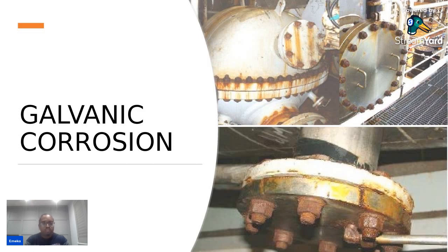So where does this type of corrosion occur? Anywhere there are dissimilar metals, so dissimilar pipe spools, screw fittings, bolts, flanges, framework and supports, instrument fittings, and also pipework and pipelines, where these two dissimilar metals are coupled together.